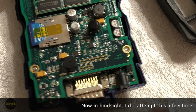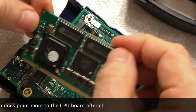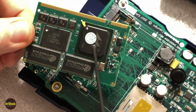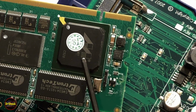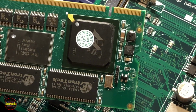So now that tells us conclusively, this is typically where you might find some errors on this board here. This board contains the brains of the whole thing. So over here is the microcontroller, or the MCU. This is a Marvell PXA 270M running at 520 megahertz.